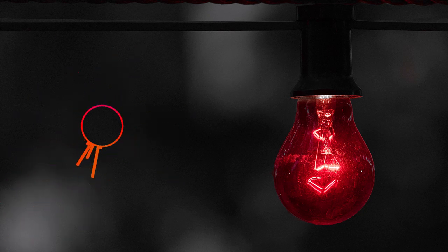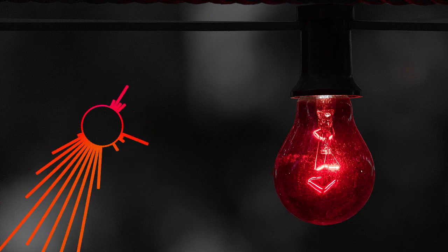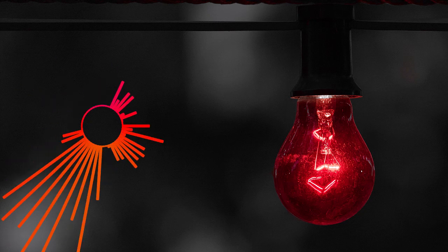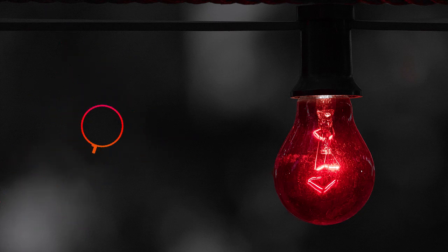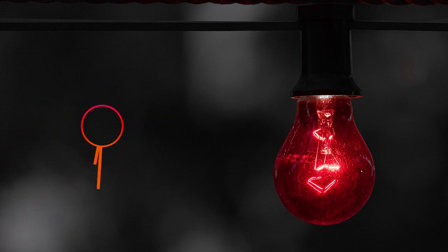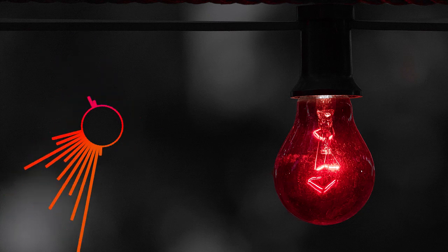Okay, so what does all this mean for you as a future electrician or technician? Here are a few takeaways. LEDs don't have filaments to burn out like incandescent bulbs or gases to leak like fluorescent tubes. That's one reason they last so long, often 25 to 50,000 hours or more. Because LEDs are electronic components, they need proper drivers, kind of like ballasts for HIDs or fluorescents, to control the current and voltage.